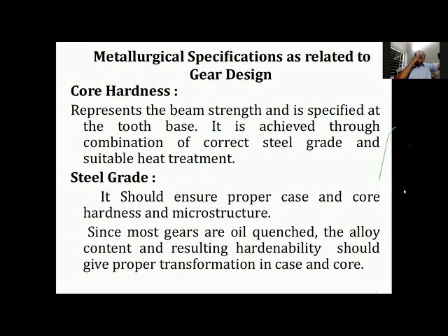Now, one other thing is that core hardness has a major function in the performance of the components, specifically the gears. Many researchers have found that if we plot a graph of core hardness versus fatigue properties, it looks like a bimodal distribution. Actually, it is not a bimodal distribution. It is two fatigue versus core hardness curves superimposed upon each other.